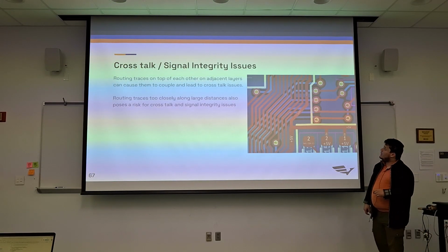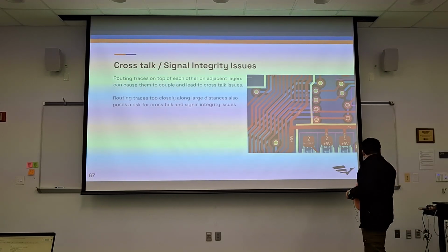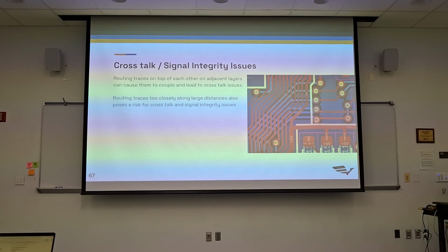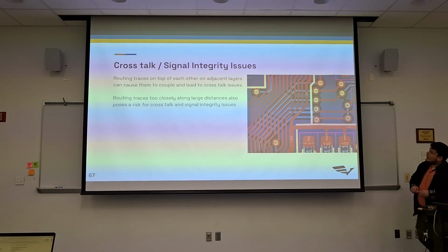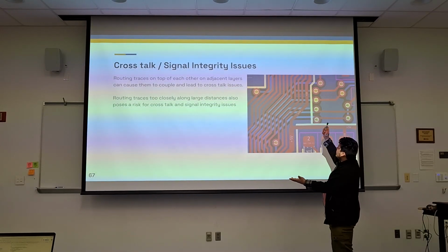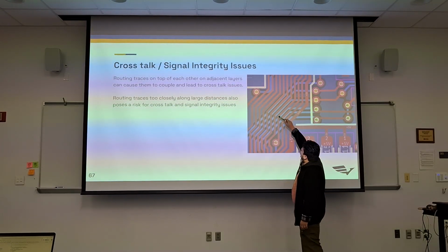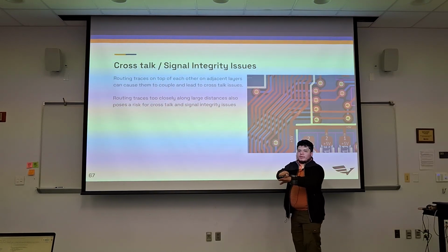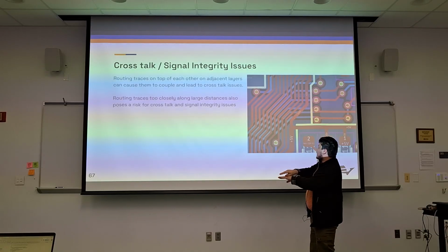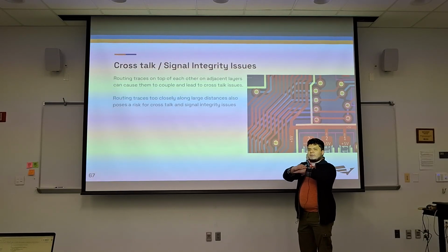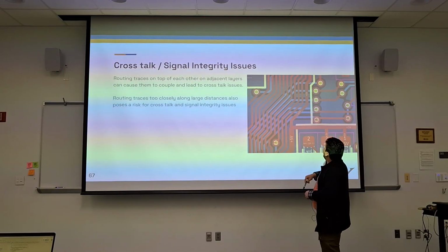Crosstalk. This one hurt my soul when I saw that one, because essentially what we have here is coupling, where these are on opposing sides. This is only a 2-layer board, so top and bottom. And so here we have signals on top of other signals. And so those are now coupled together, electromagnetically speaking. And so that's a big no-no. You never want to be on top of another signal ever, right? So always avoid that when you can.